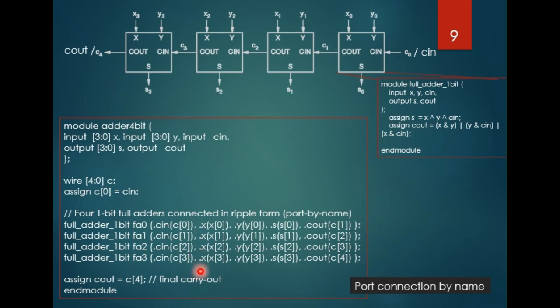So this method, though a bit longer in terms of describing the instance, as you can see, we need to type the port name every time before we put in the top level signal. But it has the advantage where you don't need to follow the ordering you defined or declared earlier in the sub module.